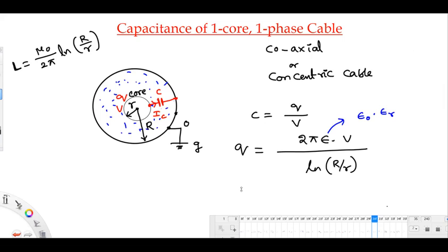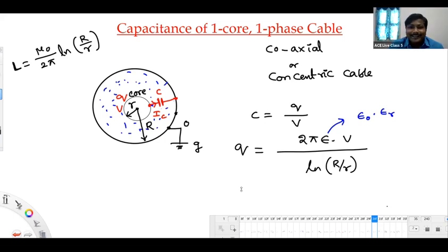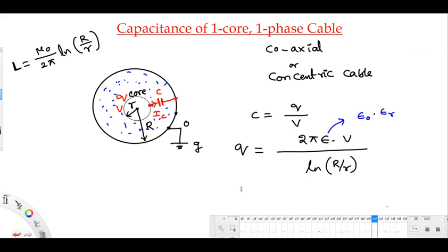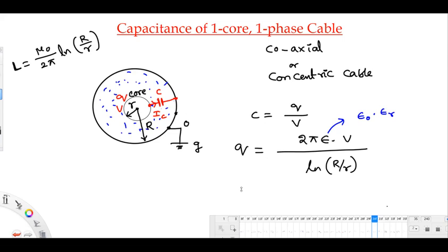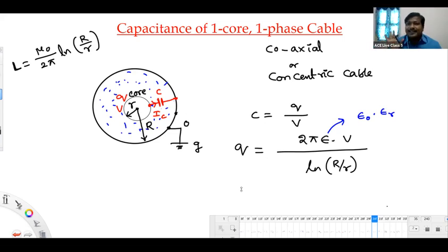If we consider the ideal condition, the real power should be zero here. But practically, you don't have ideal conditions, you have to consider losses. Then P2 will become P1 plus power loss. P1 plus power loss is the real power consumed by the synchronous condenser.